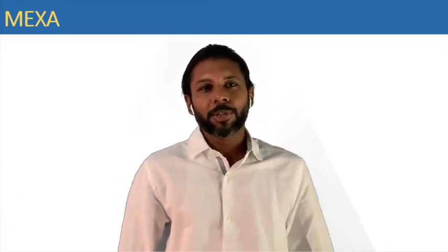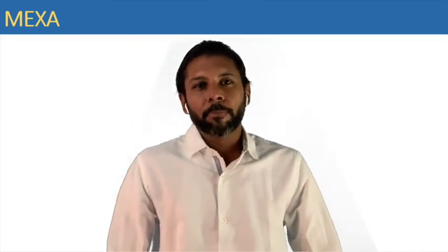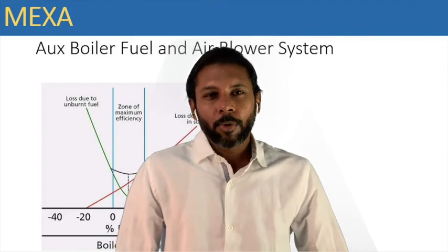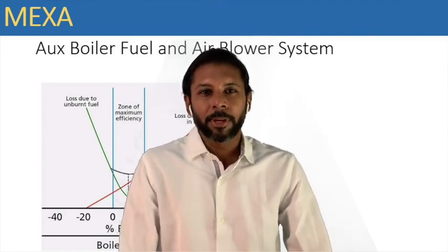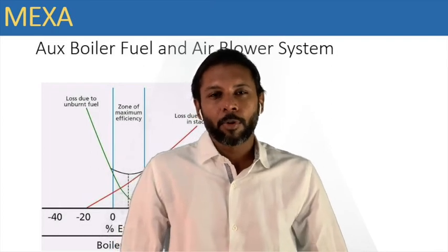Fuel and air blow system. Almost all boiler burners are designed to handle fuel whose viscosity ranges between 2 cSt and 17 cSt. And also it is designed to support the pumping systems of fuel which are associated with the boiler burning. For complete and efficient combustion to happen, the right quantities of fuel and air need to be mixed. About 14 times as much air is required for efficient combustion to happen.